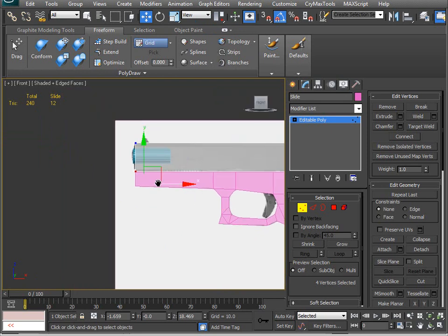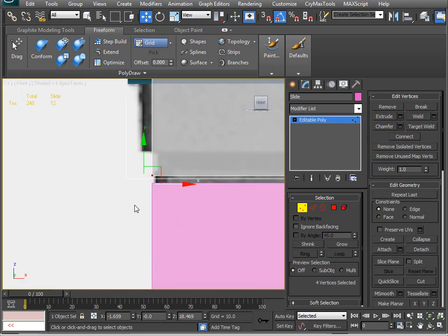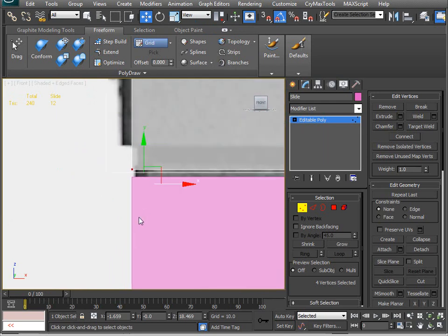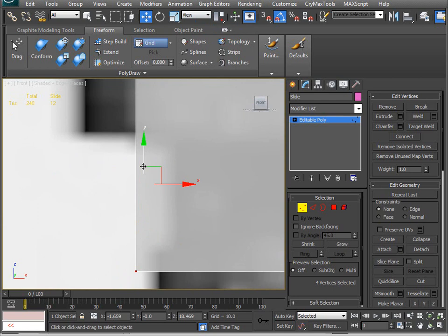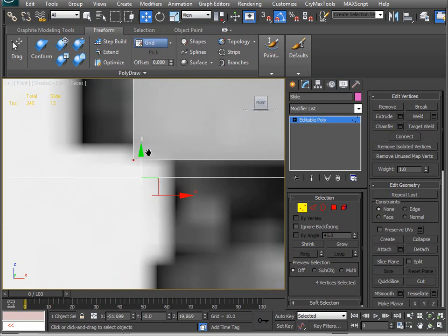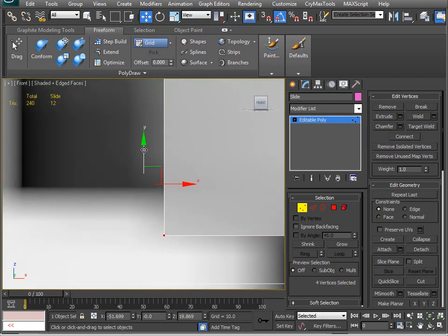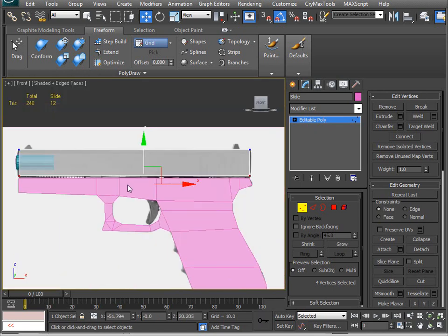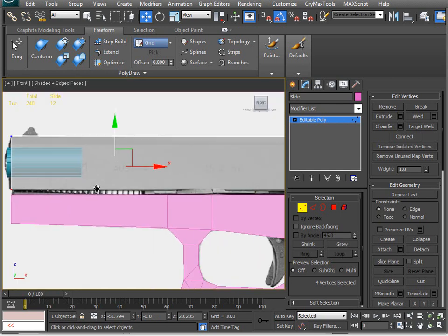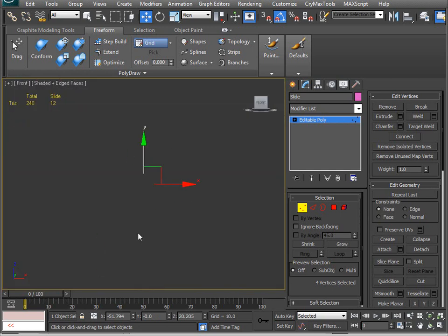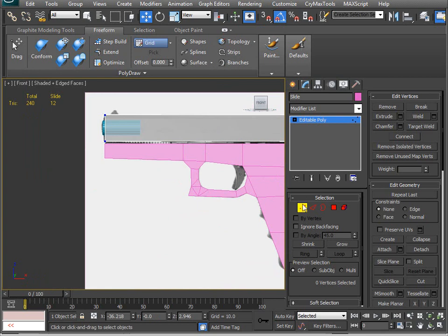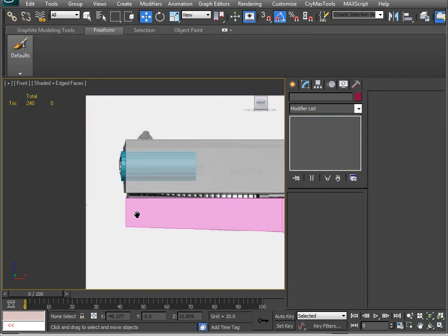And now if I move my object, you can see that my transform gizmo moves with it, but once I let go, by using middle mouse, I can zoom in nice, move this up, zoom in a little bit more, move this up, and I can say, okay, I'm dead on that pixel if I really needed it. Okay? So this is a nice one to use. Like I said, lets you look anywhere and still have your gizmo. I'm going to just put that back to the center. Come off of here. Now I can click off this object.